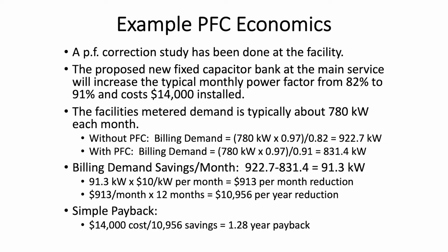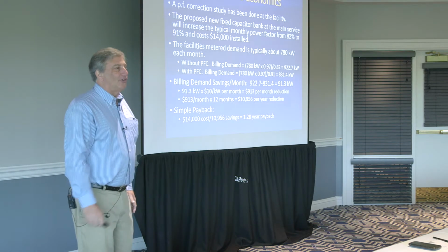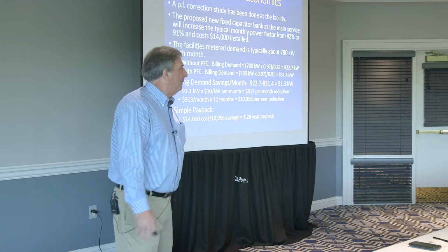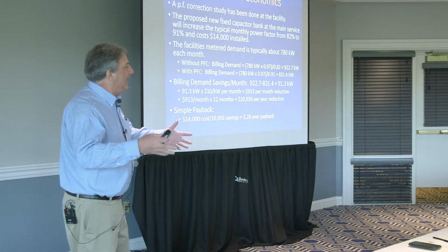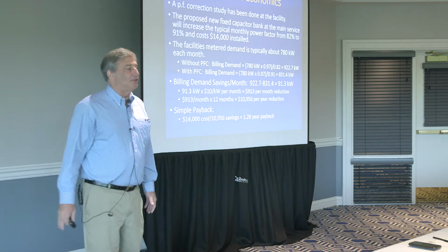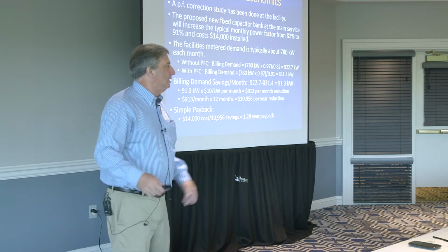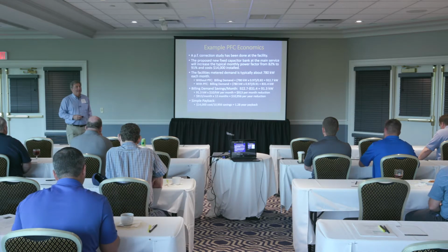And that's the idea with power factor correction. Once we know what the power factor is that we're starting from, and how many capacitors we need, it's pretty straightforward to get to my installed cost for that equipment. We do the calculations, it says what we can save, and we get a payback.